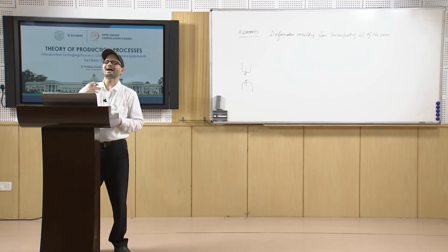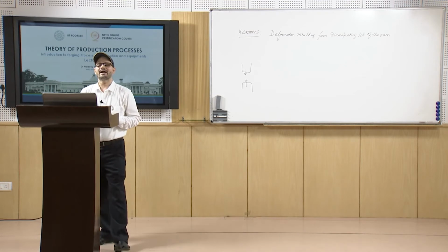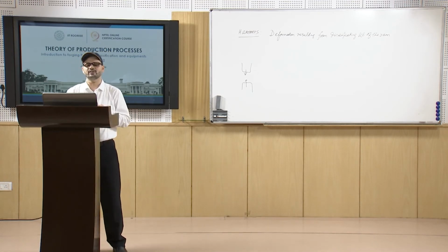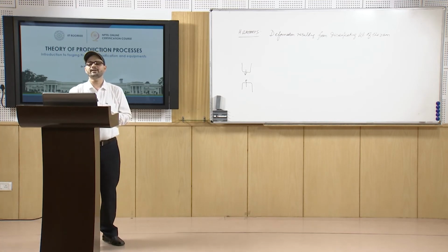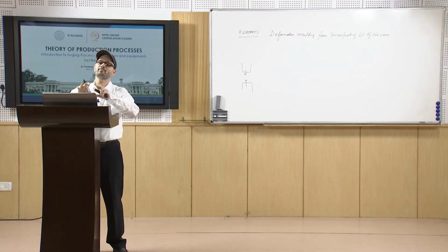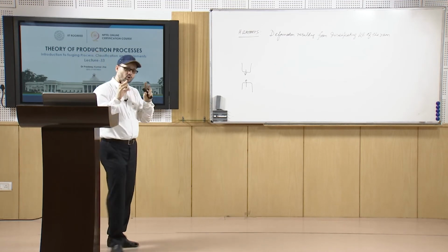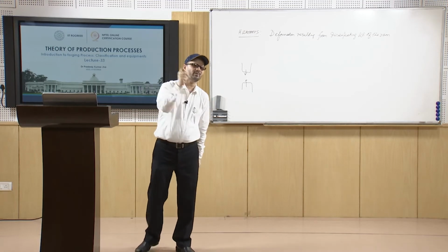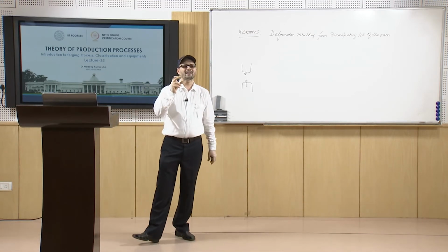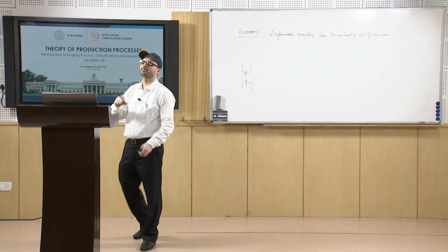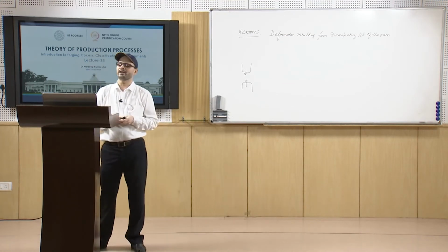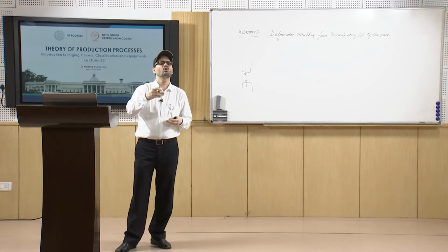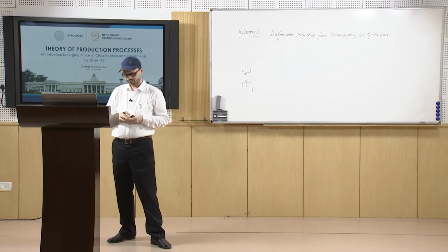Similarly, you have hydraulic presses. In these hydraulic presses, the capability of carrying out the forging operation is limited mainly by the maximum load capacity. That is why, in these hydraulic presses, you have a hydraulic medium to apply the load. Since the capability is limited chiefly by the maximum load capacity, these hydraulic presses are known as load restricted machines.